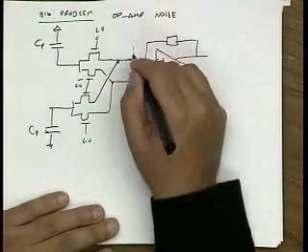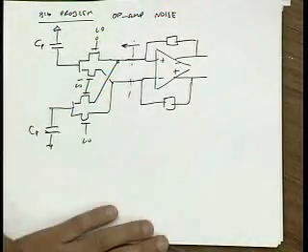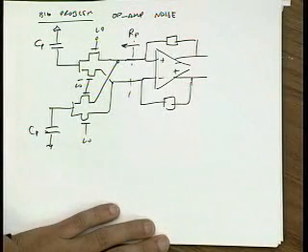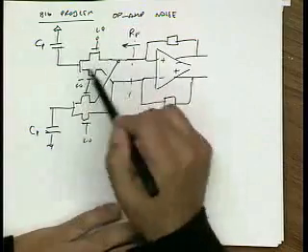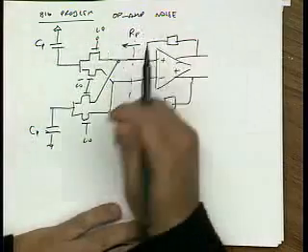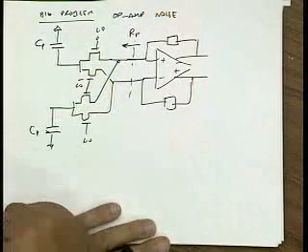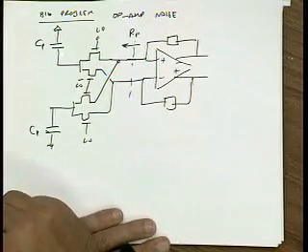If I look back out here, it turns out that I see a resistance. Let's call that RP. Okay? Where does that resistance come from? It actually comes from charging and discharging these capacitors. If you're familiar with switch capacitor circuits, this is how we build a switch. Basically, this is how we emulate a resistor using a switch and a capacitor.